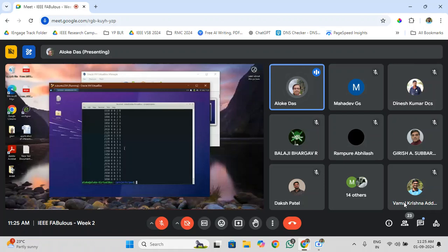That's why the open source community has given another wonderful software, GTKWave. After running this a.out, see, another file is created, pwm.vcd. The test bench is written like that, so that this VCD file is created. This VCD file will be used for this. You have to load that VCD in GTKWave. This is the way, GTKWave, then the VCD file.